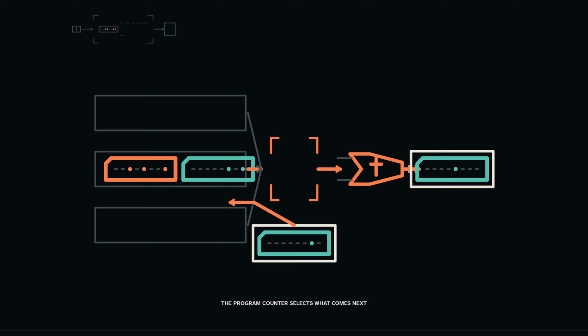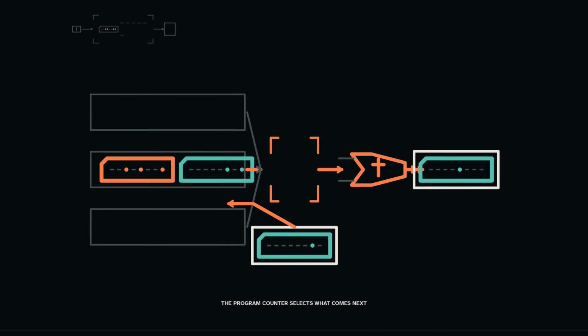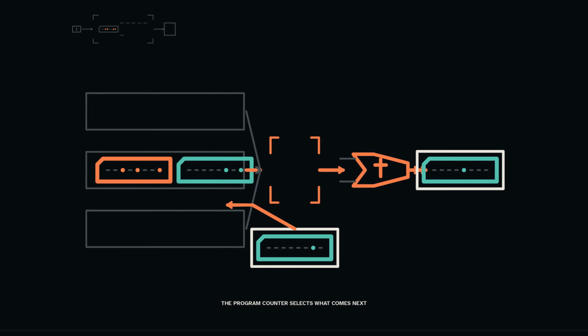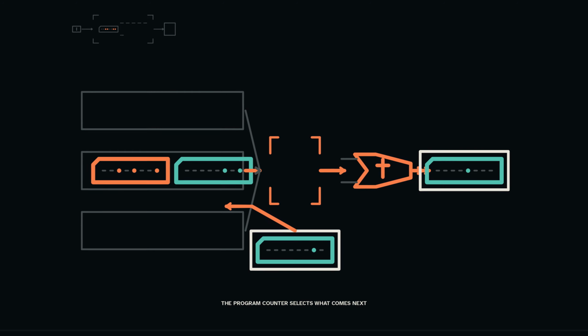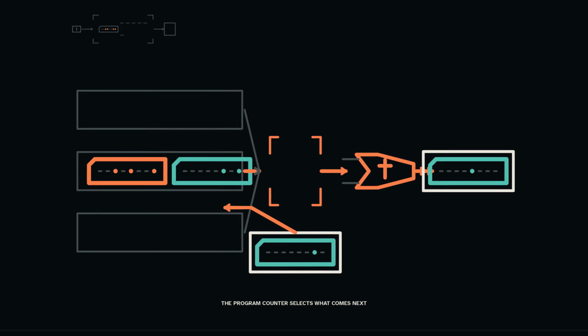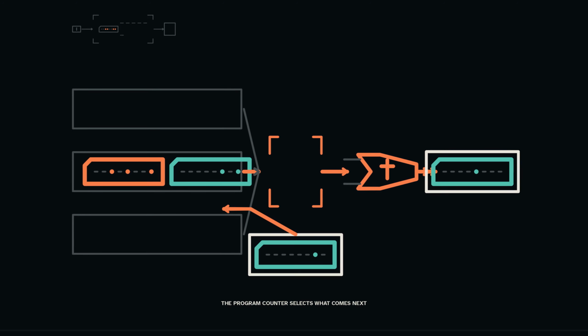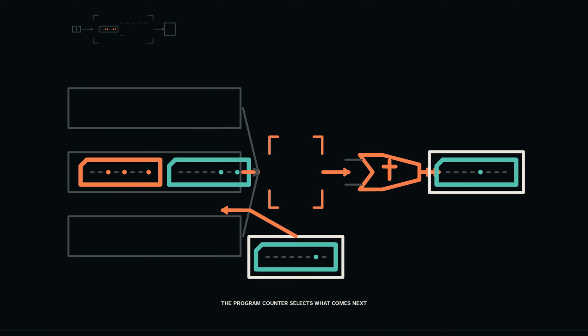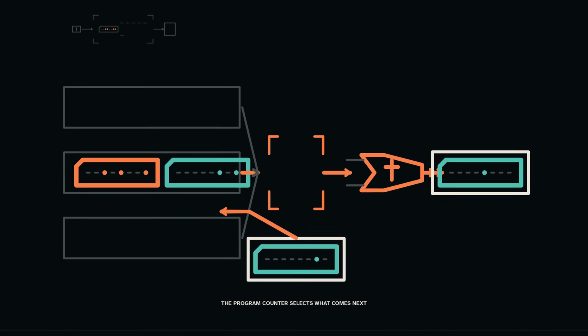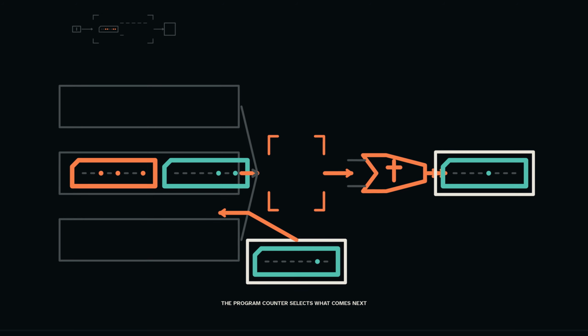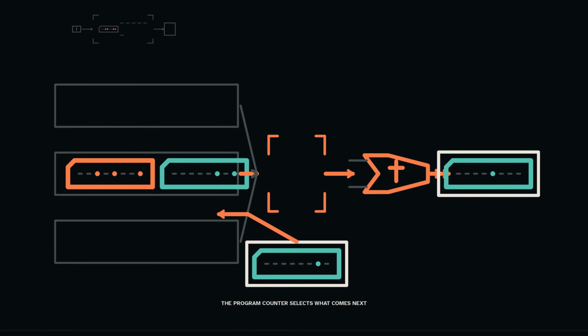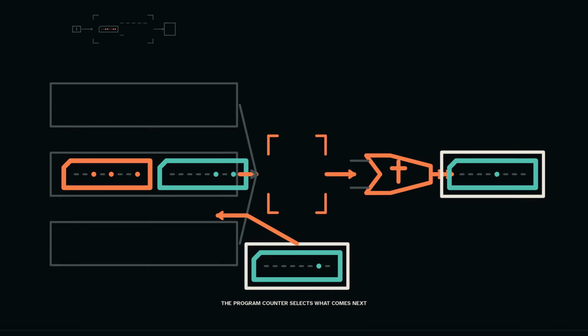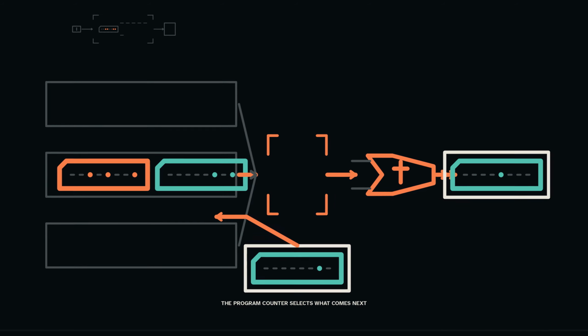Predict 2 rolls for hexadecimal 05. In an operand position, it may mean immediate 5. At an opcode position, it is decoded through instruction fields and may be illegal. At a data address, a load may copy it without treating it as control. The pattern never announces its role. Controller state, address route, and instruction contract establish whether the byte is fetched as instruction material or accessed as data.